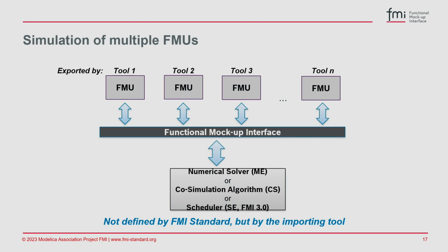Also, if you have multiple FMUs, you can decouple them from this numerical solver or co-simulation algorithm. The communication is via the standardized interface, and the solver or co-simulation algorithm is not defined by the standard, but by the importing tool.